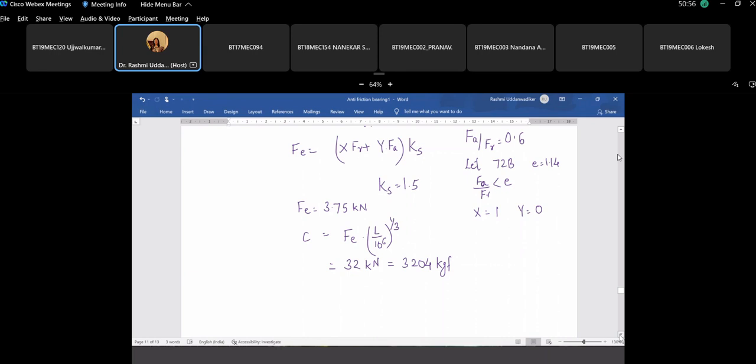Last two digits multiplied by 5. So the shaft diameter comes out to be 55. Whereas in our problem, the shaft diameter is 50 mm. So if you go for 50 mm shaft diameter, it is 7210B, for which the load carrying capacity is 2900, which is not sufficient for this.